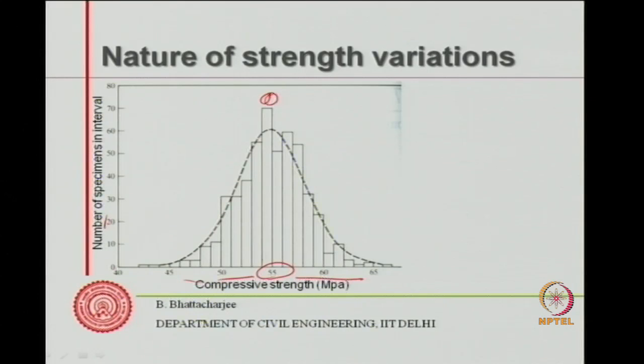For example, it will depend upon the error in mixing, proportioning. First of all, what we call batching. There would be some kind of error in batching. You wanted to put 180 liters of water, your measurement system might have put it around 180 instead of 185, or 190 instead of 185. There will be some tolerances about the actual quantity, specified quantity of water you want to mix.